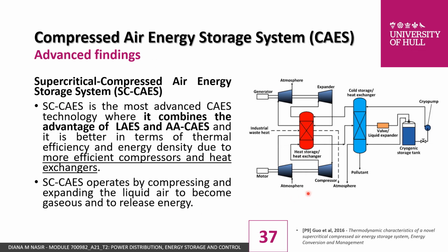The next finding is to integrate the advantage of the LAES and also the thermal energy storage adiabatic CES, where it uses liquid air to replace the normal air. The liquid air has higher density than the normal air and it can store energy for a longer lifespan, while the thermal efficiency is improved by improving the efficiency of compressors and also the heat exchangers.